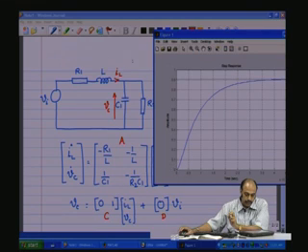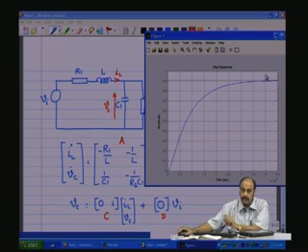Then as time progresses, the capacitor gets charged through the current here and the voltage starts building up, and in the steady state, that is in the DC condition, capacitor is open once it is fully charged, and during that time R1 and R2 share, because this is 1 ohm and this is 10 ohm. So, 10% goes to R1 and the remaining 90% goes to R2. So, this is how one, and the rise time is as given here. So, it takes roughly something like 4 milliseconds to reach 90%.